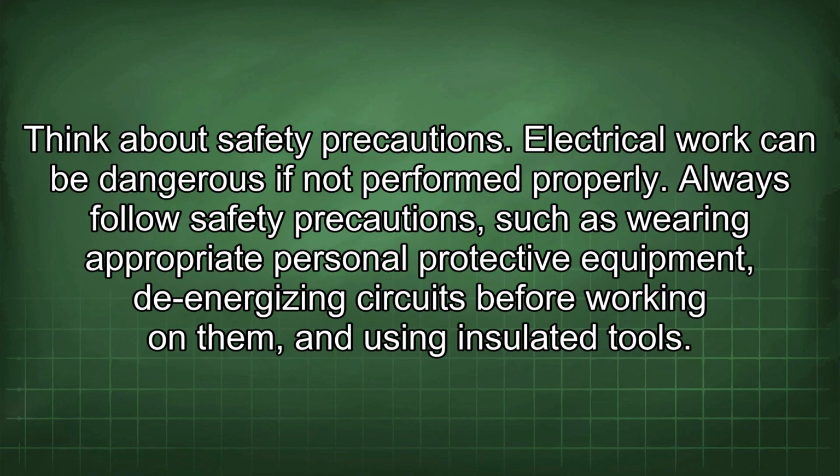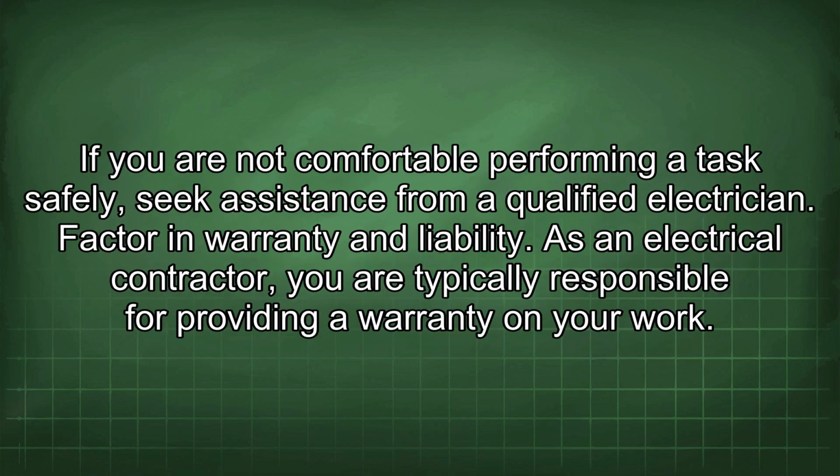Think about safety precautions. Electrical work can be dangerous if not performed properly. Always follow safety precautions, such as wearing appropriate personal protective equipment, de-energizing circuits before working on them, and using insulated tools. If you are not comfortable performing a task safely, seek assistance from a qualified electrician.